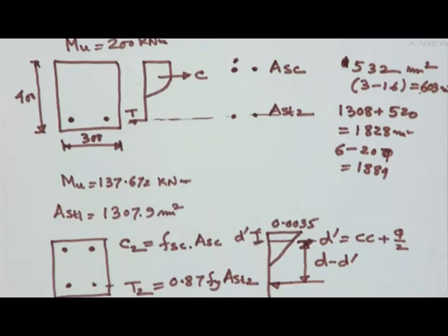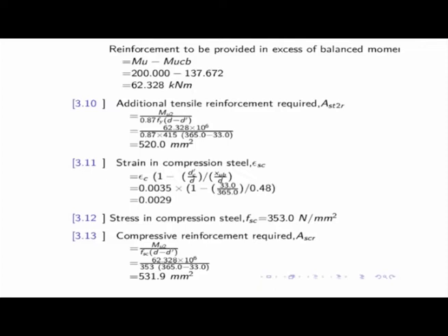So this is the one you can do. This way you can find out the values. I hope that it is clear, because life could be very simple if you provide the same diameter bar. But as you all know, life is not so simple. Life is very much complex. So economy, safety, so many other things are there. So in this case also, it is better to go ahead with 16, or if possible, 12 millimeter dia bar also you can use.